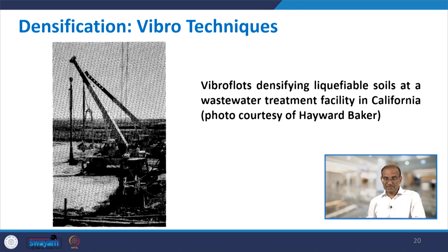And how it is used: here, vibro floats densifying liquefiable soils at a wastewater treatment plant in California. These are photographs taken from Kramer's book, and this is coming from Hayward Baker. In this case you have a crane, in fact you could see in this figure there are two cranes, and these vibro floats are suspended from the cranes and put down in a grid pattern at different locations.